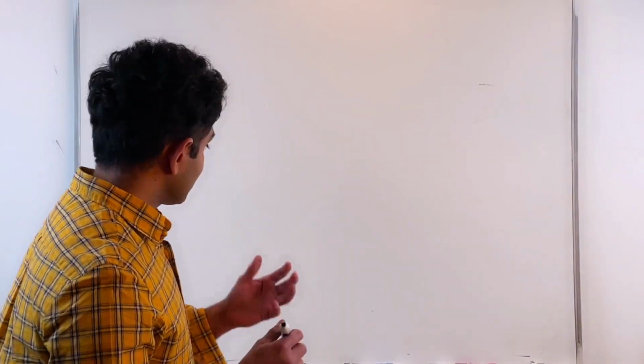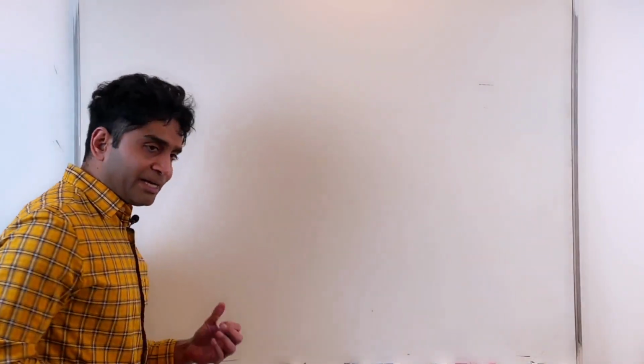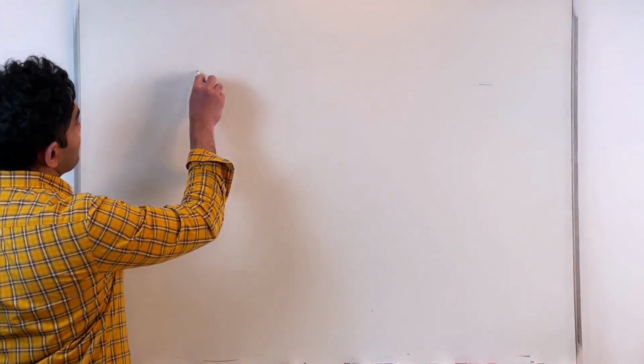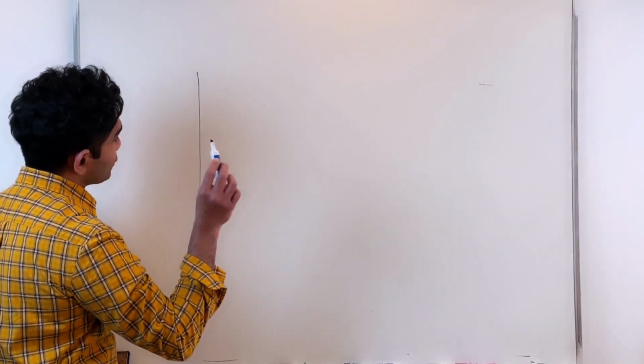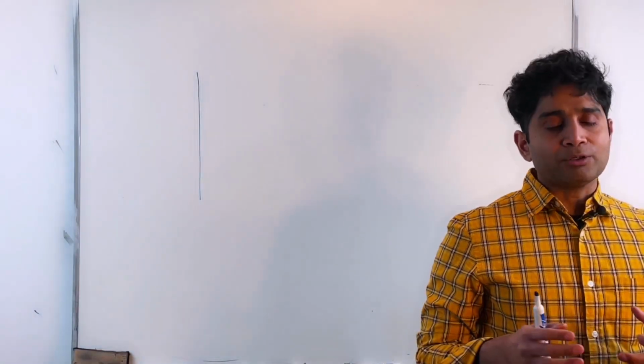Okay, all right. Now, in the design of decimal systems or decimal adders, again, I'm trying to design a single digit. We are going back to the modular design approach when I'm trying to add an n-digit decimal number. We have seen that the addition operation at every individual digit position is exactly the same. You're adding two digits together along with the previous carry. You're getting a sum, in this case a decimal sum, and a carry out.